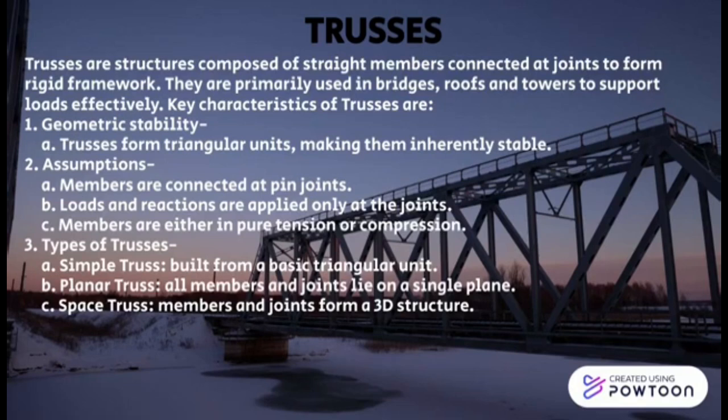Assumptions: members are connected at pin joints. Loads and reactions are applied only at the joints. Members are either in pure tension or compression.